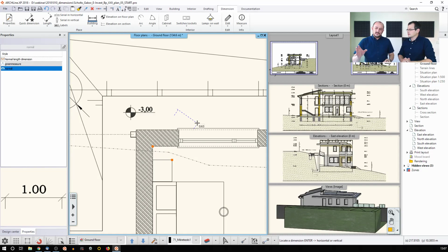But in this specific case, I'm not that happy with this, because I would like to see either the vertical or the horizontal distance, but not the real distance. This tool allows you to switch between modes during runtime. The default mode is the real distance. The second mode, which I activate with a right click, is the horizontal component of this distance.